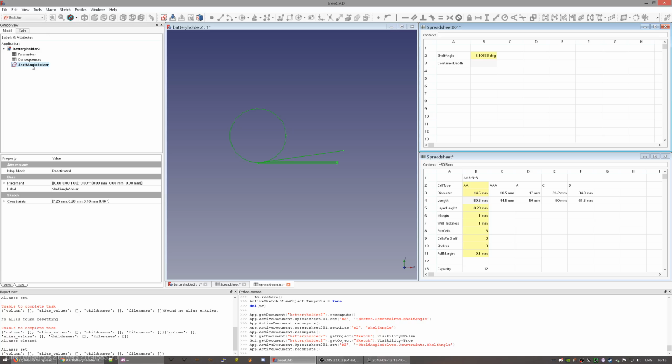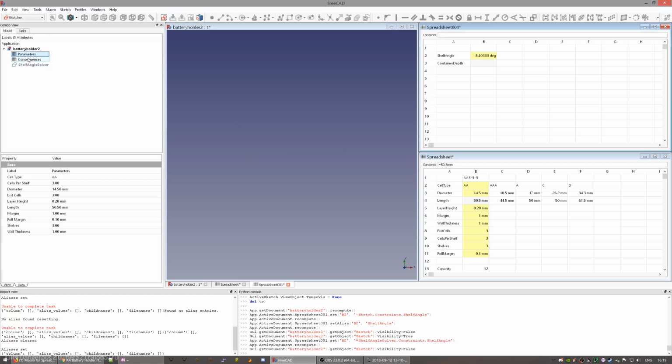So if we are careful to always name our objects such that they form one word as far as FreeCAD symbols are concerned, the limitations are a little bit more distinct than that. I think it's something like C symbols. So uppercase and lowercase letters A through Z. Digits and underscores are allowed, but not as the first character. Anyhow, we can use these names, but I find it easier to just have these two, parameters and consequences, to refer to.